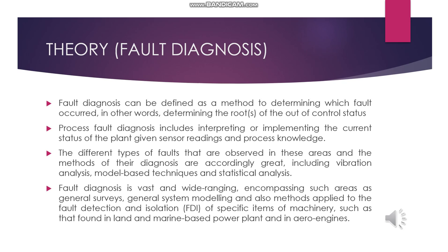The methods can be categorized into data driven, analytical, and knowledge based approaches. Meaning of out of control status: when points on a control chart move outside the upper or lower control limit, the process is said to be out of control.